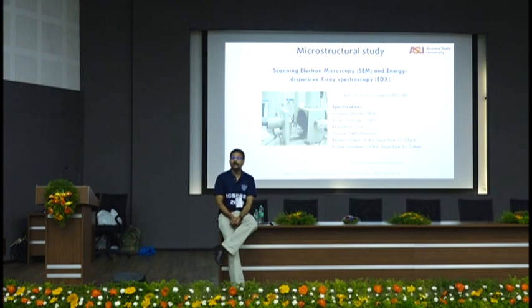Now, what will you have in CSH? Do you think CSH is a very homogeneous thing? No. CSH is very, very heterogeneous. The silica tetrahedron, remember the Si4 tetrahedrons, right? Now, is your CSH in cement paste two-dimensional or three-dimensional? I showed you the model, the Feldman-Sereda model for CSH. How did it look? Did you see 3D in that? Layered, right? Any layered structure is a 2D structure. You have a mat on the floor. Is a mat 2D or 3D? 2D, it's a layered structure. So CSH is a 2D structure.